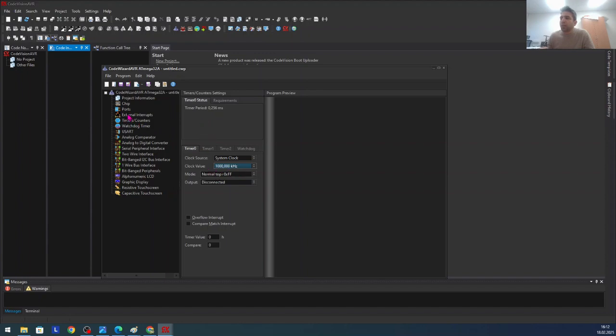Then later you come and change your chip frequency, let's change it to 4 here. Then let's see what is in the counter. The 1 megahertz became half because it is following the chip. It is working with the frequency from the chip.